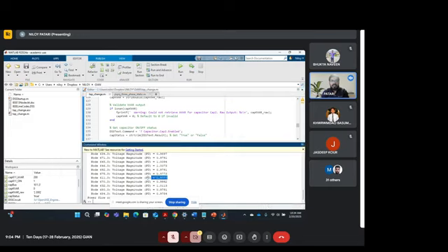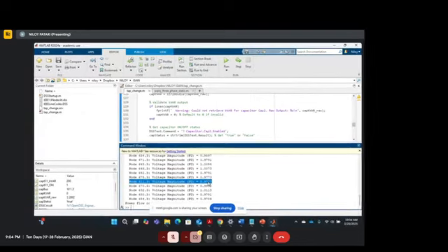Okay, see now that your voltage has been boosted, right? Initially it was 0.9608, now it's 0.97. Now you can do it differently. Here I've just shown voltage, but you can also check in terms of measuring power flows. Just in front of the capacitor you put a meter, and in the meter you measure active and reactive power flows. And obviously with a 100 kVAr capacitor and a 200 kVAr capacitor, your reactive and active power flows will also change by a very small bit, right? So you can put a meter also, but this is a very good representation.